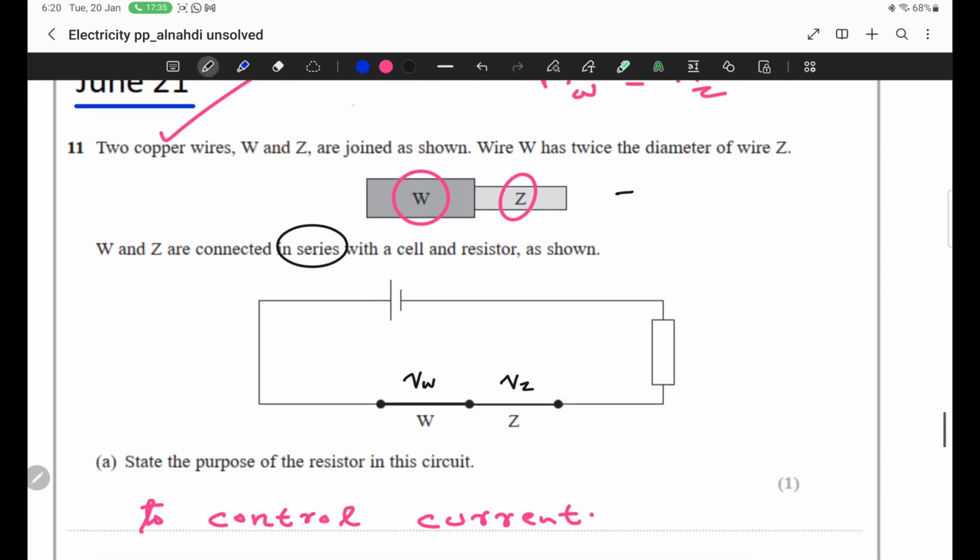You are right. And the equation is I equals n e A v, drift velocity. As it is clear, sir, current is same everywhere. Material is same everywhere. E is same. So drift velocity is inversely proportional with area, and area means drift velocity is inversely proportional with the square of diameter. Okay, beta. And we are given some values for diameter.